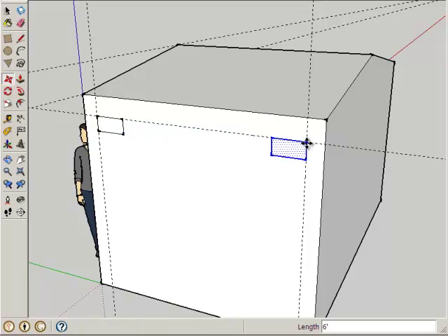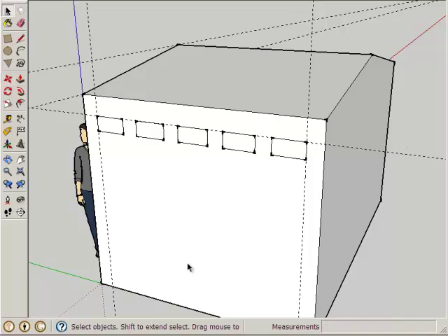And now you may recall that I can create multiple copies that are evenly spaced by putting slash and then typing in the number of copies I want. Let's say /4. So 4 copies plus the original is 5. Is that enough? Maybe that's too many. I'll live with it. Okay, press the space bar for my select tool.